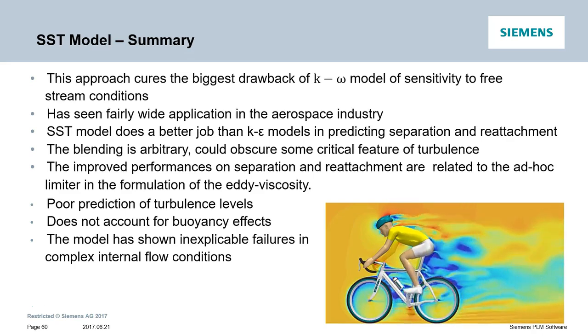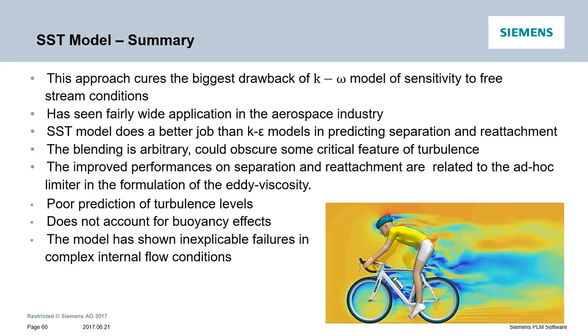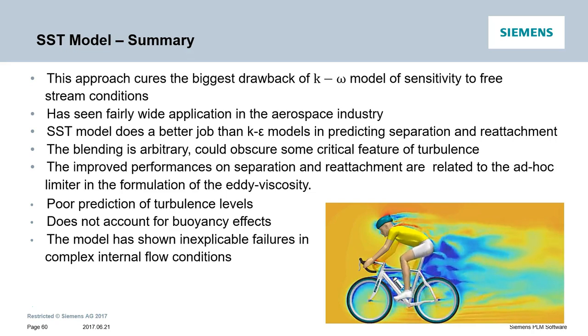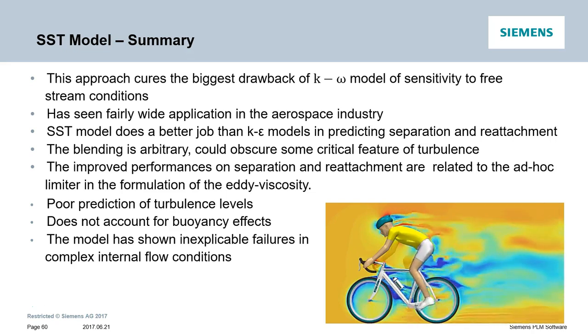Essentially, the SST model does a better job than the K epsilon model in predicting separation and reattachment, though it struggles a bit in capturing buoyancy effects or complex internal flows.